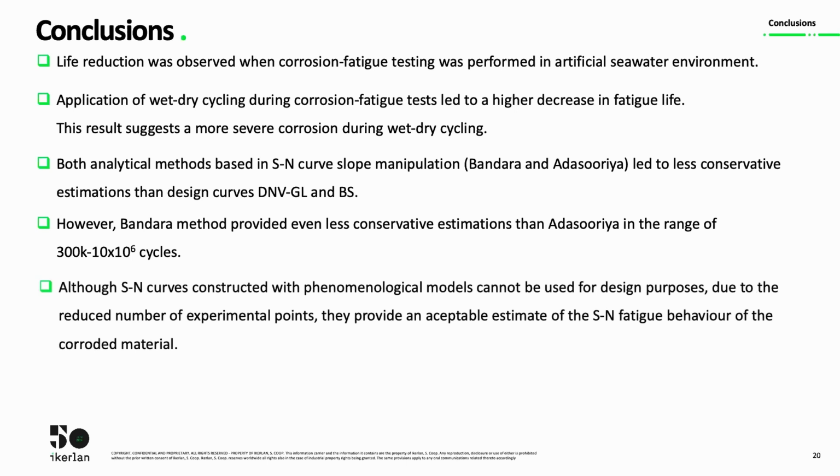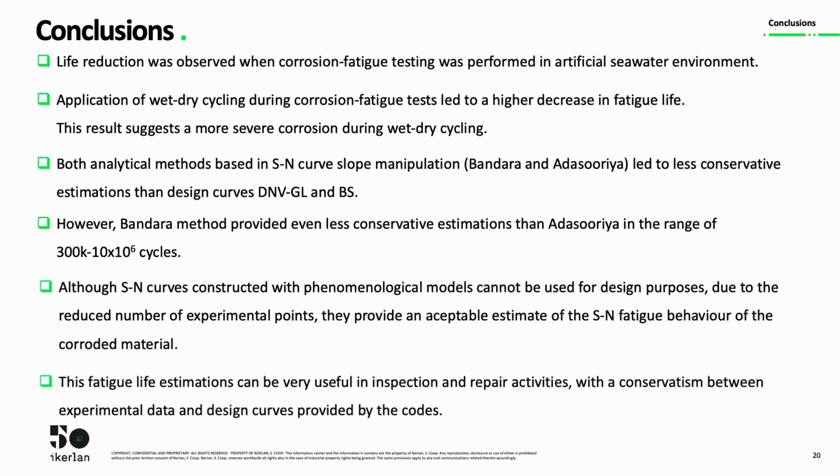Although SN curves constructed with phenomenological models cannot be used for the same purposes due to the reduced number of experimental points, they can provide an acceptable estimate of the SN fatigue behavior of the corroded material. And finally, these fatigue life estimations can be very useful in inspection and repair activities, given the observed conservatism between experimental data and design curves provided by the codes.